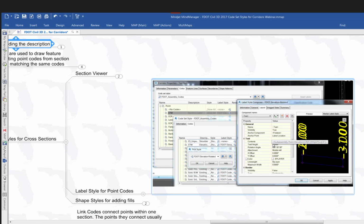Because you don't really know what's being assigned to that edge of traveled way until you actually find the code and where it's being used. And you'll find that in the corridor properties. So if you start there and then just drill down through the user interface, then, if you need to, say, change a precision setting, or maybe the offset distance away from the label, the Y offset for the label, those are some of the things you might need to make some minor adjustments to in the style.